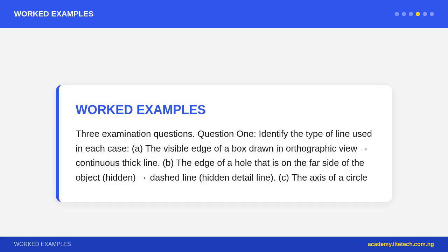Lettering in technical drawing. Letters and numbers in technical drawings must be clear, upright, and uniform. Use single-stroke lettering, no serifs, simple strokes. Standard height for general notes, 3 mm or 5 mm.